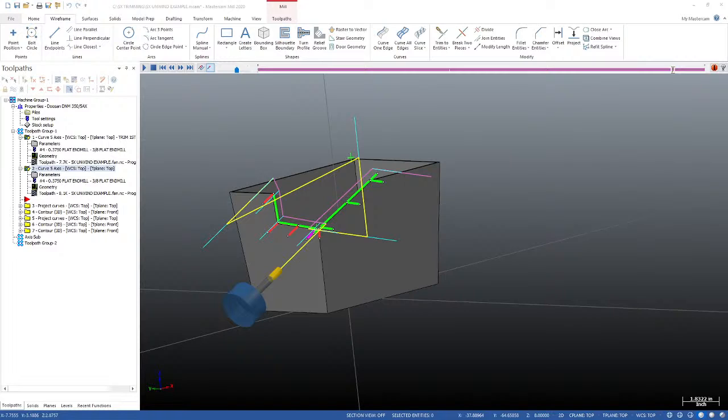So you've got an E32 HSK spindle on it, 40,000 RPM, but the E32, it's only 32 millimeters in diameter, right? So you're talking about a 1.25 inch diameter tool holder. The ideal size tool for the Micro Center is probably 6 to 10 millimeters for roughing, and then I've used tools on that thing that are 0.01.